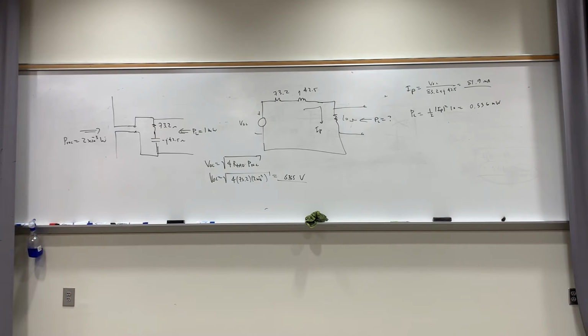After that, then we get into chapter 7, and that's waveguides, and we do rectangular waveguide equations, right? There are 2 modes, TE and TM, right? Okay? Now, I don't expect you to memorize the field equations for either, but you do have to know that for TE modes, the impedance will always be the characteristic impedance of the region, eta naught, divided by the square root of 1 minus (fc over f) squared, right? And for TM, it's the square root of 1 minus (fc over f) squared times the characteristic impedance. And this is important.